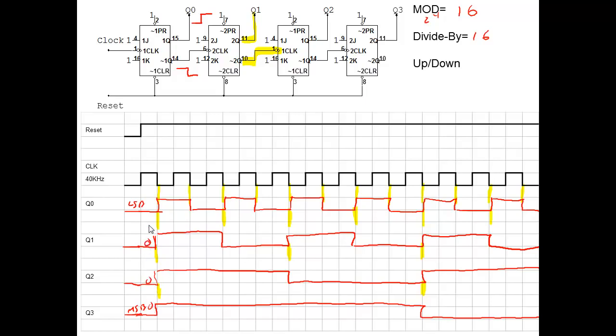So we've got 0, 0, 0, 0, 1, 1, 1, 1, 1, 1, 1, 0, and 1, 1, 0, 1. So here we have a 0. Now we've got a 15, 14, 13. Well, now what does it look like it's doing? Well, it sure looks like it's counting down to me. It's going lower as we go across. So this is how you make a down counter out of negative edge triggered flip-flops: you do it by doing the inverse of them.